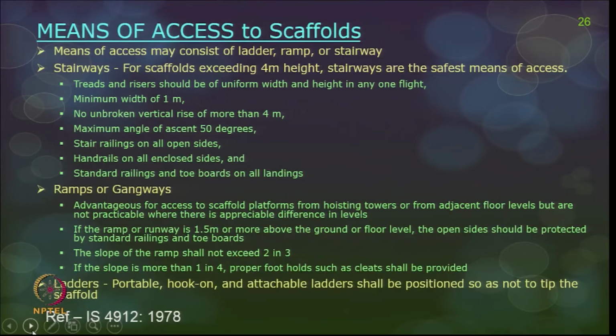Otherwise, a ladder is the safest means of use if it is for a short term purpose, and ramps are also used for easy lifting and movement of materials. For scaffolds exceeding 4 meters in height, stairways are the safest means of access.